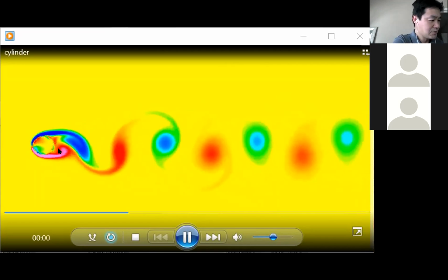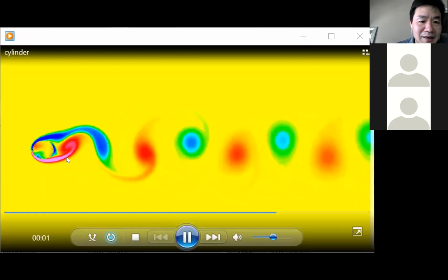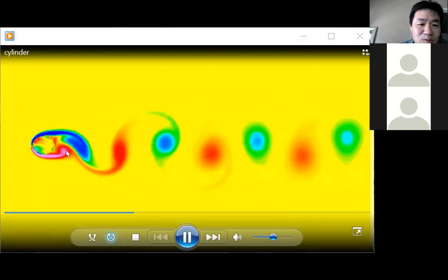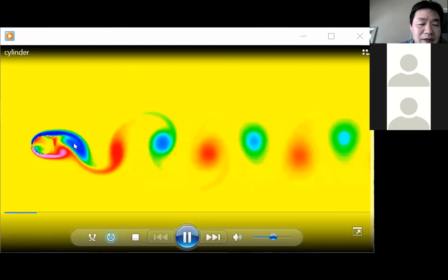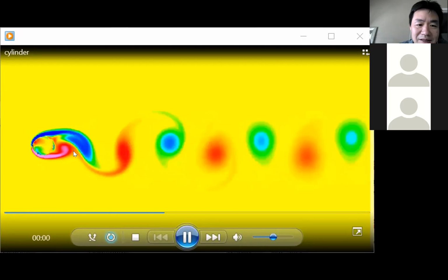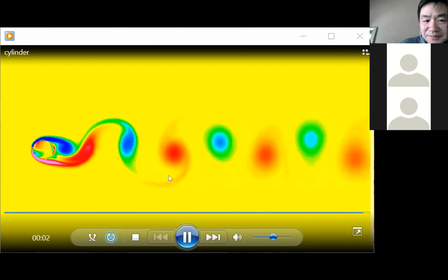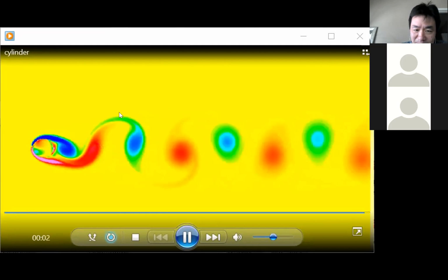I think also in the textbook it has some pictures. Page 298, figure 6.13, also shows some detailed flow structures of flow over a cylinder. But that's the flow. What does the flow look like? The vorticity is a vector, so it has positive and negative. The red is positive, blue is negative, but they have the same strengths. It's just a direction. So one on the top of the cylinder, one on the bottom, gradually. This is called vortex shedding. So that's the flow phenomenon.